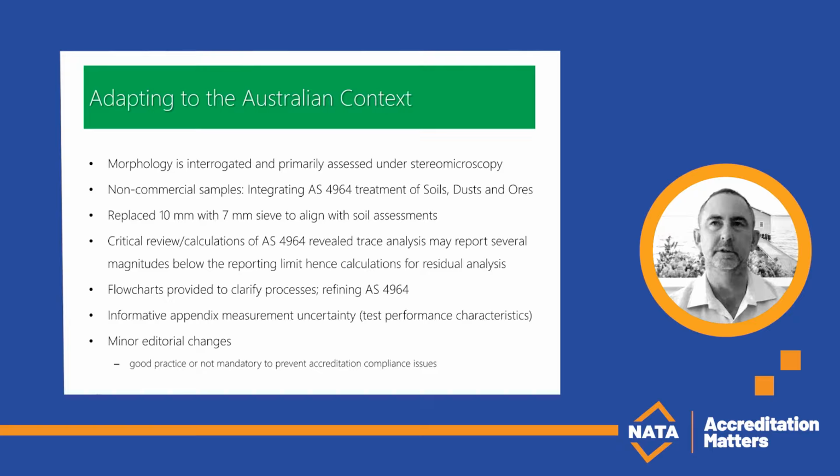The verification of trace analysis, now termed residual analysis, has been enhanced by implementing quantification of identified fibres to improve the accuracy of the reporting limits. There's also flowcharts from AS 4964 that have been refined to simplify and clarify the process. There's also an informative annex on measurement uncertainty that's been included to address test performance statistics. So don't be surprised if there may be a requirement in the future to estimate this.